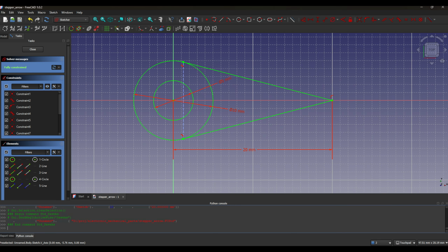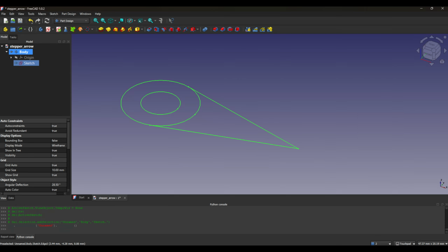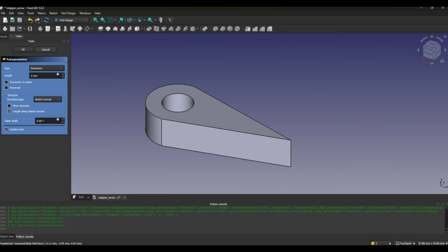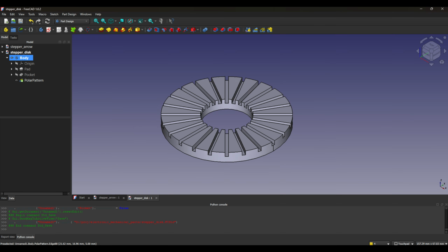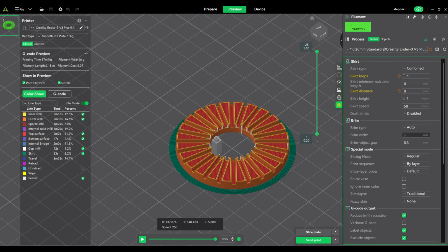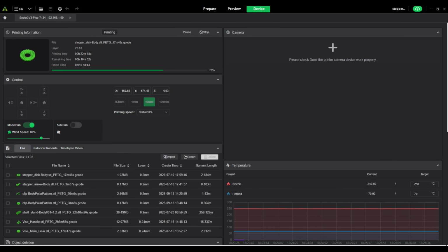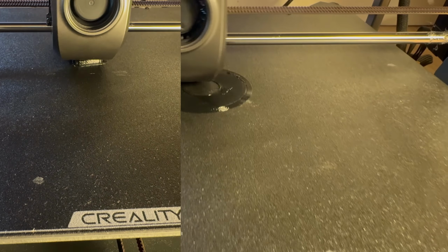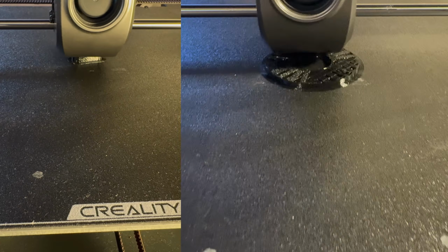Before building the final demo, I designed a small mechanical indicator in FreeCAD. The idea was very simple: create a disc and an arrow that can be mounted onto the stepper motor shaft. After modeling the part, I exported it, opened it in a slicer, prepared it for printing, and printed it on a 3D printer. This is a good example of how embedded systems, electronics, mechanical design and 3D printing can work together in one project. Even a simple printed part can make testing and demonstration much clearer.